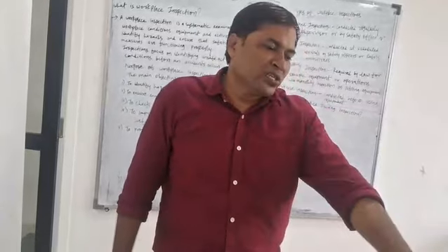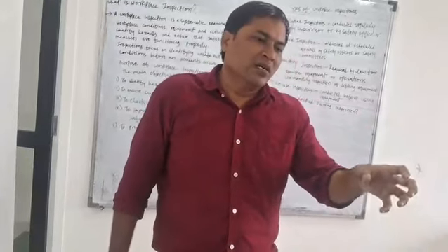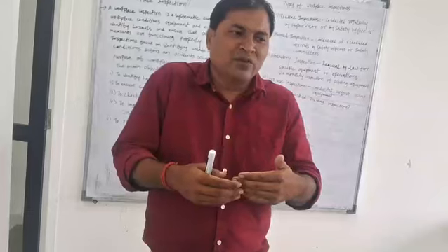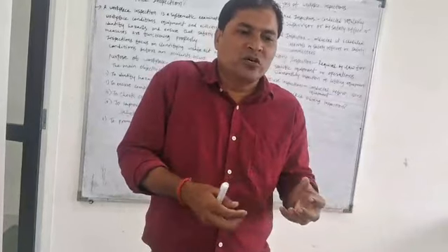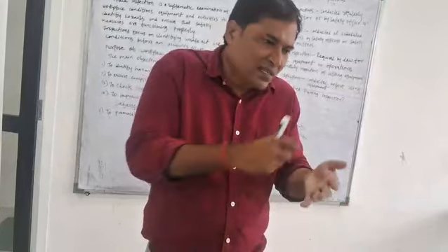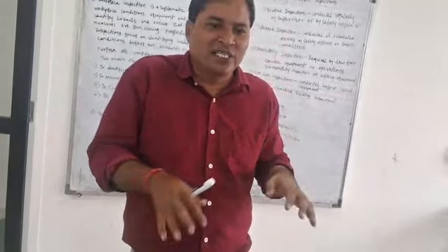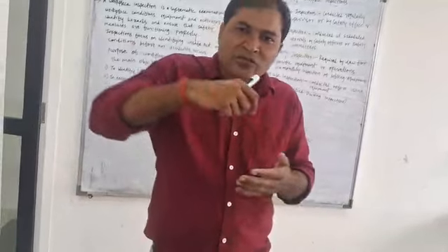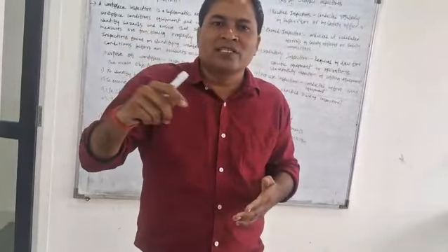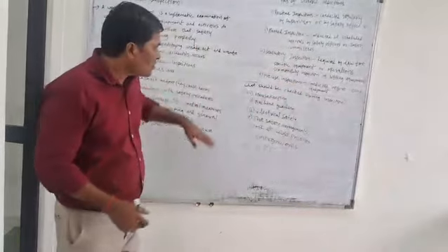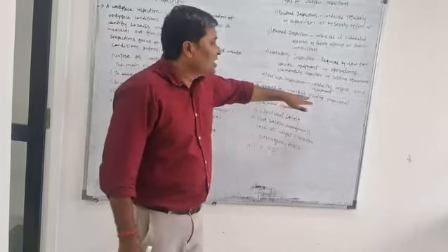If you want to run the machine in a proper way, before you start the job, check the pre-use checklist, take the points, check each and everything: wire connections, buttons, everything is in working condition. Once you fill that pre-use checklist, then you have to start the job. That is very important.